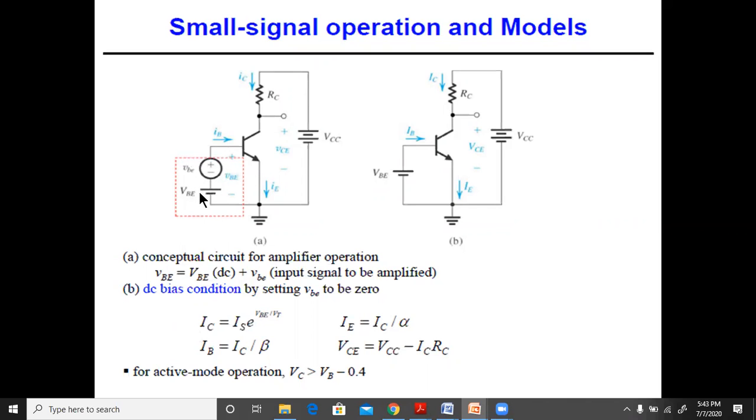So remember that this DC VBE is only because of the biasing. And that biasing, if you consider the voltage divider bias, is because of the two biasing resistors R1, R2, as well as the VCC, which we have connected here, right? In the last class we have connected here, or might be the collector to base bias. Due to the collector to base bias, whatever is the voltage at the base, that also can be considered for VB.